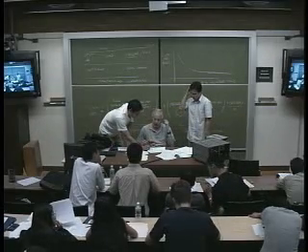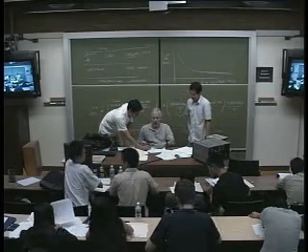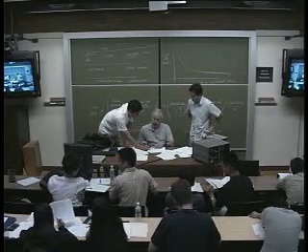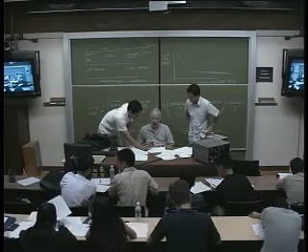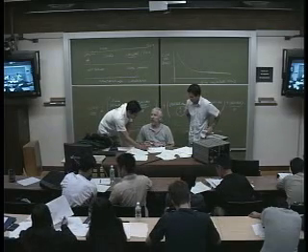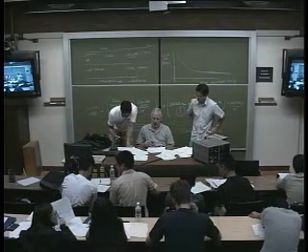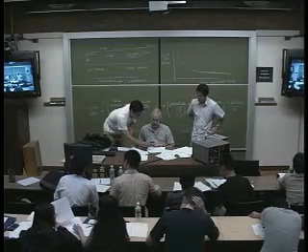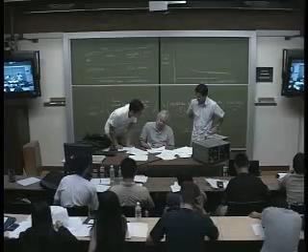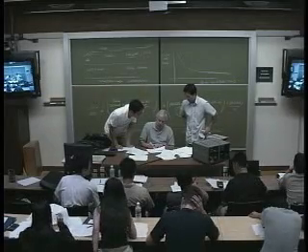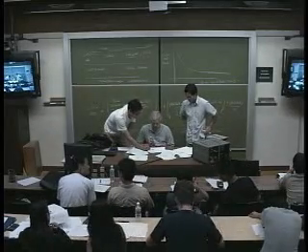It would be pretty tough to match all those currents and small VT variations. This is just to limit the upper swing on this. Well, there's no swing here, hardly. This is like a diode connection. This connection limits the swing on this node. Yeah, effectively. It sets the voltage there, reduces it down to keep this in saturation. Looking up into here, what do you see? You see the diode connected transistor. So looking up this way, it's 1 over GM. So there's no gain.